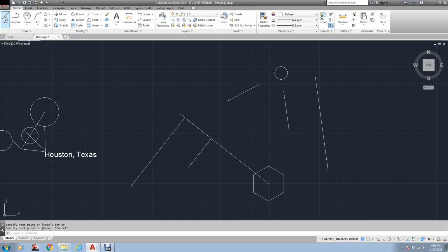Okay, the first thing everybody wants to do is they're going to go PAR, and they come over here and they click. Well, then nothing happens. Okay, and they're like, it doesn't work, Mr. Dobson. Okay, so you start a line, you type PAR, enter, you hover over this. I am not selecting anything. Once you see the two little green lines, you just come back. Okay, if I came over to here, see those two green lines? Now watch, it's going to go parallel to that one for me, see?